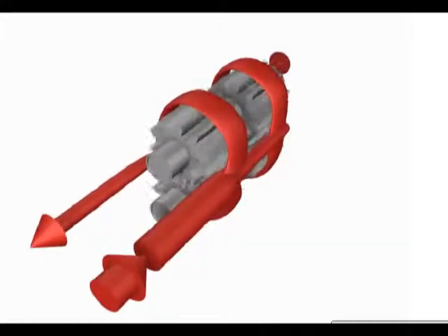The fluid between the gear teeth and the housing is carried around to the opposite side of the gear section. As the teeth mesh, the fluid is pushed out of each outlet port. The gear sections are connected by a common shaft, which causes all of the sections to rotate at the same speed. The inlet flow is divided proportionally between each section.